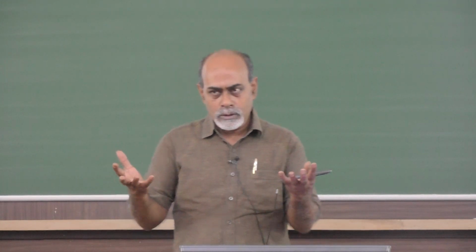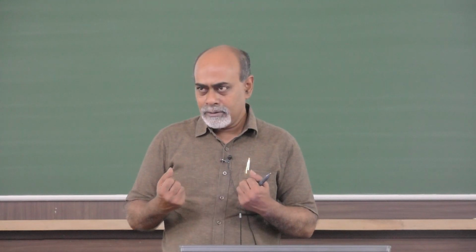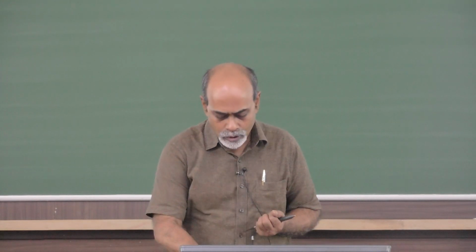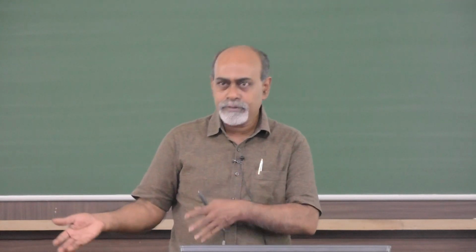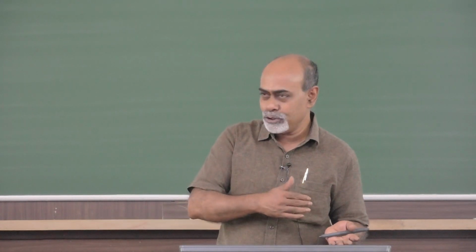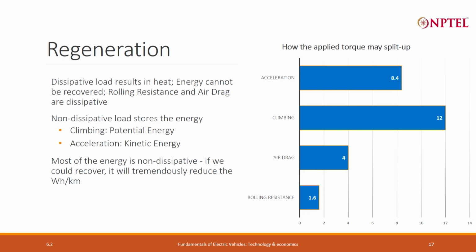So, I want to recover the energy, but keep the motion in control, and the normal way it is done is that I will let the vehicle drive the motor and let the motor in turn generate electricity rather than consume electricity, and put that electricity back in the battery, which I can then draw whenever I need in the manner I need. This reversal of torque, it is not reversal of motion, it is not that the vehicle is running in the reverse direction or the motor is rotating in the reverse direction, it is the torque that is getting reversed. Instead of the motor driving the vehicle, the vehicle is driving the motor.